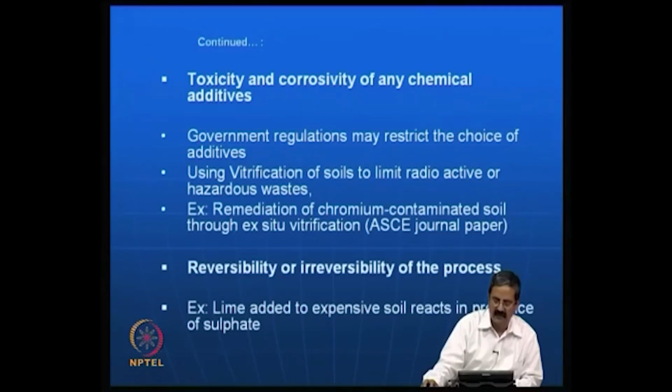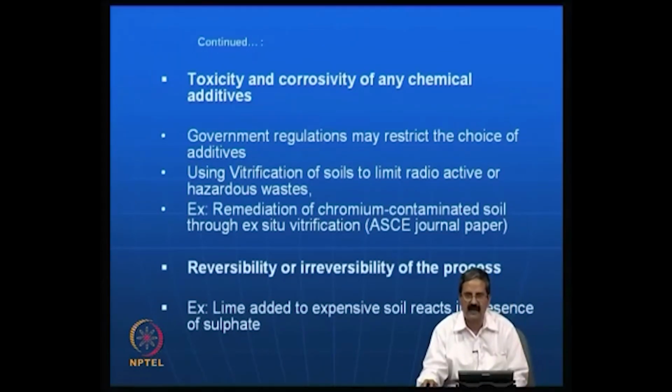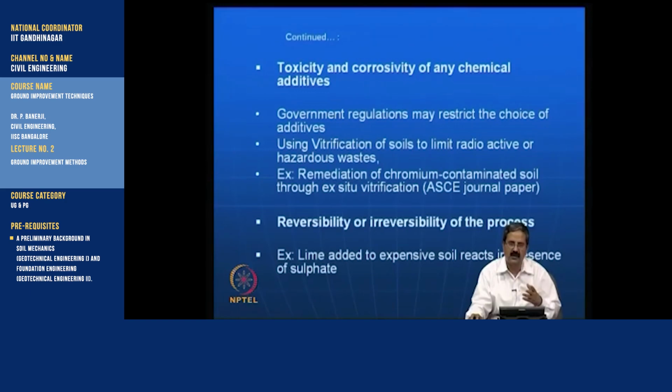But you have seen that, particularly when sulphate is present in the soil, the expansive nature comes back, and the heave will be more than you expect. Say for example, the percent heave may be 5% in one case or 10%. When the sulphate soil is present, it is so bad that whatever stabilization you have done becomes useless.